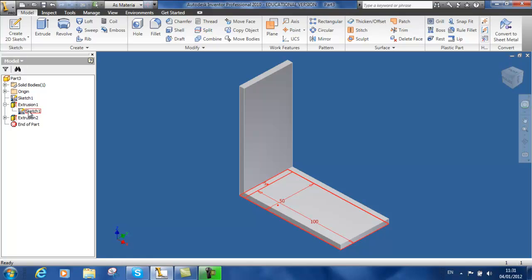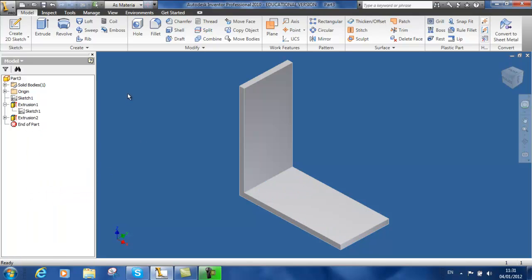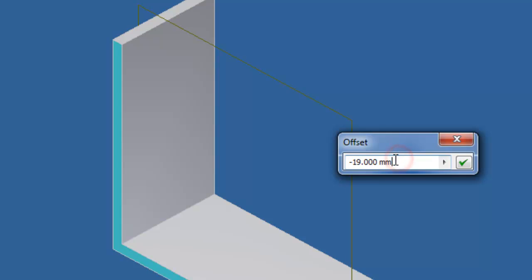This particular angle section could represent the structural item of a piece of furniture. So the best thing is to strengthen the actual component as best it can. So I'm just going to click a plane, click on the edge and drag it in. At this point it looks for an actual measurement to be inputted from the front face.